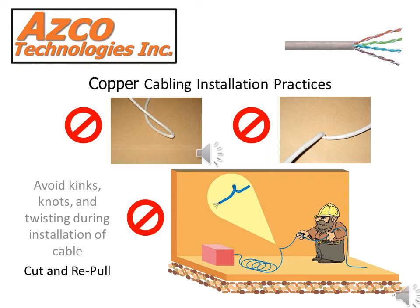Copper cabling installation practices. Today we'll be referring a lot to Cat5e, also known as twisted pair cable, or UTP, a common cable used for telephone and network cabling. It is important to avoid kinks and knots and twisting during the installation of this cable. If you do have a kink or a knot, or it doesn't pull easily out of the box, cut the cable and re-pull again.